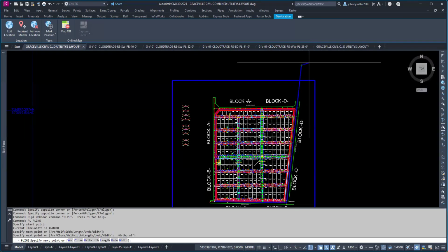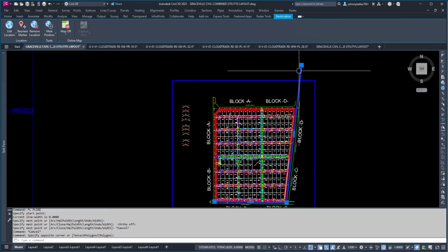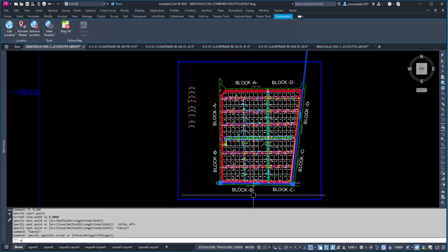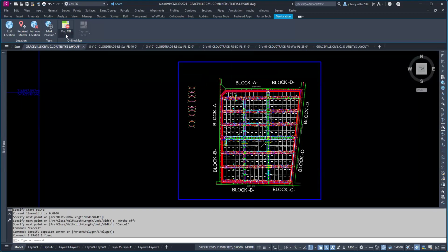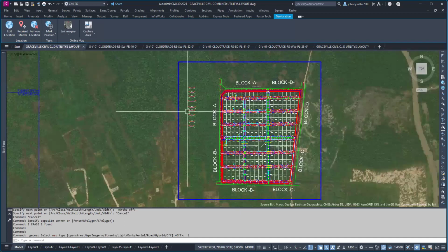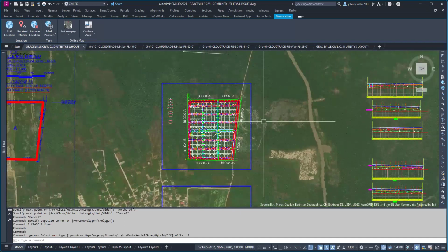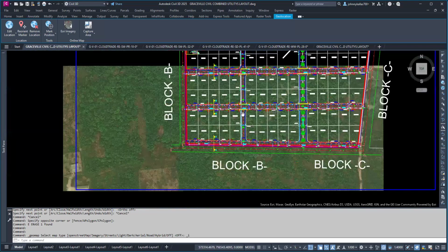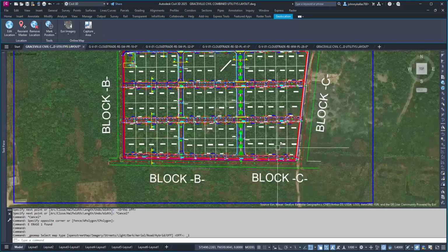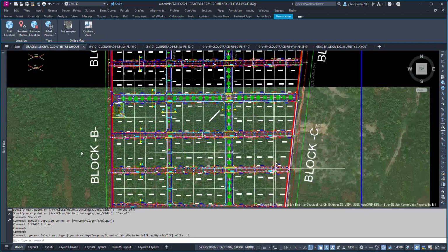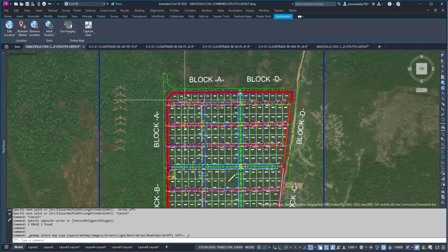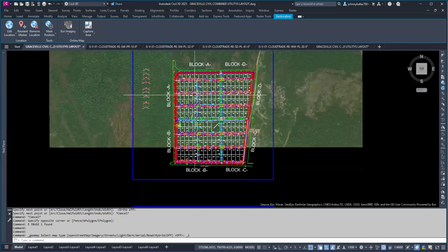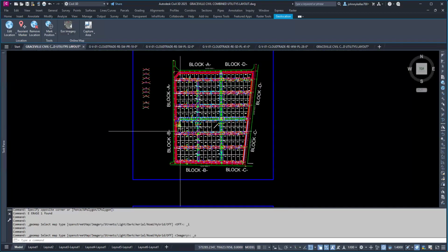So for us to have the flow, we should raise it up to 4 meters. And in addition, if we have heavy rain around and this place is full of water, there is no way for the water to enter the Graceville project. So the maximum will be 3.9 and the minimum will be 2 meters.